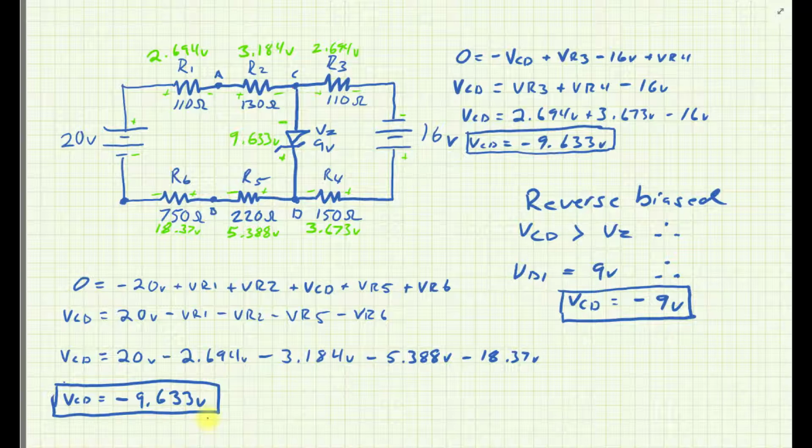So all that being said, basically what I do know is that since I have greater than 9 volts, the diode will hold that voltage to be 9 volts as long as it doesn't exceed the specs and explode or burn up. As long as we're within some reasonable spec, that diode will try as hard as it can to make it be 9 volts.